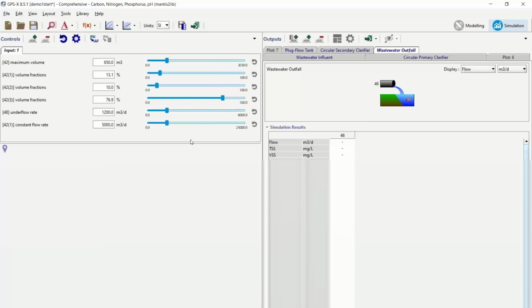You see a sort of shadow bar graph along with the one that is actually from your model. So in this case, the dark color is the model result, and then the shaded, transparent bit is actually your data point that you're reading from a file. The way to do this is to hit the data files button at the top of your menu and associate a particular spreadsheet that would have the data that you would want in it. This is basically the same as any normal data that you read in. It's just that the cryptic variable names that you've got across the top here correspond to these individual bars. So that's a handy tool that I use once in a while.